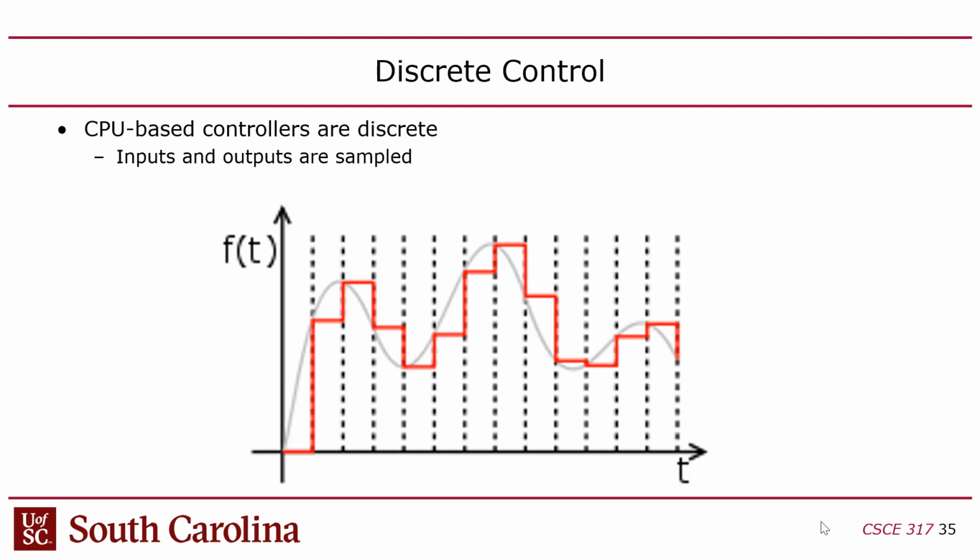And this is actually one way to do it. This isn't the only way to do it, by the way. This is called a zero order hold, which means that at every time step, you set the discrete time domain signal to whatever the continuous signal was.